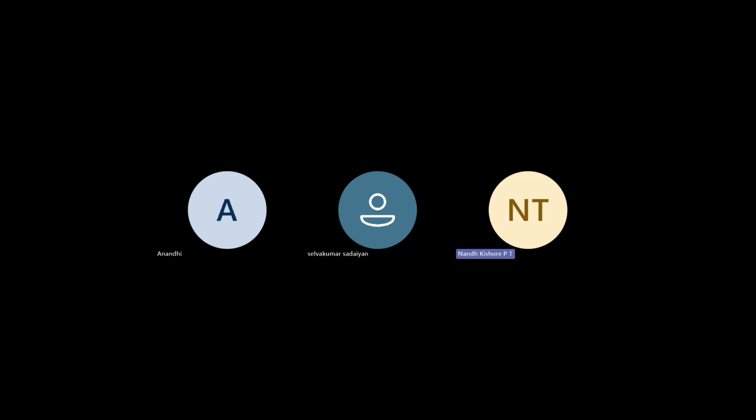Did you understand what I was telling during that time? Yes, sir. Until the diode conducts, it cannot block any voltage, so across the other device, the entire DC bus voltage will come. Okay, sir.